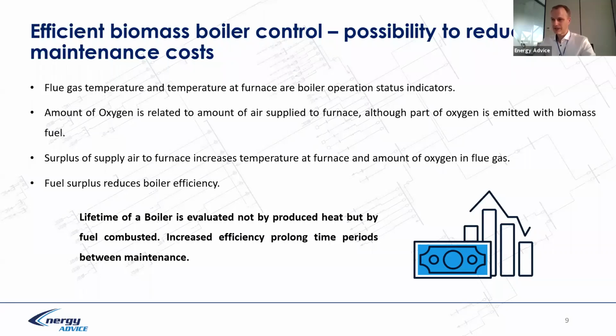Flue gas temperature and temperature at the furnace are boiler operation status indicators, and the amount of oxygen is related to the amount of air supplied to the furnace. Also, part of the oxygen is emitted with the biomass fuel. So the idea is also to reduce the oxygen amount in the flue gas, and